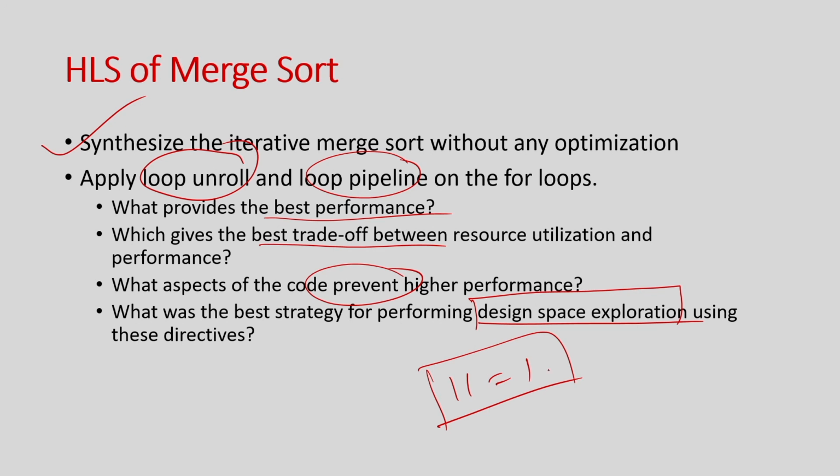So that is the maximum benefit. But if there is a 4 stage pipeline and your II is about 4, then basically the pipeline is doing nothing, right. The initiation interval of a pipelined circuit fails to be 1 because of primarily two things. One is the loop carried data dependencies, right. That means you are calculating something in iteration I,